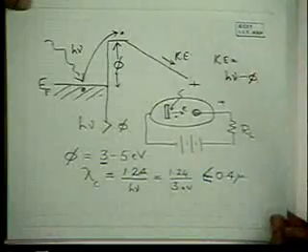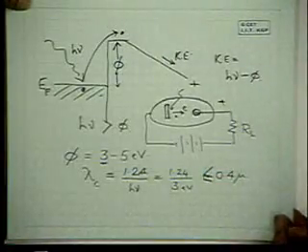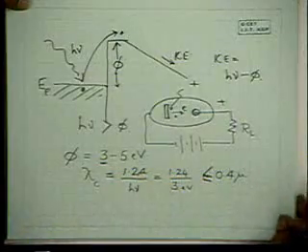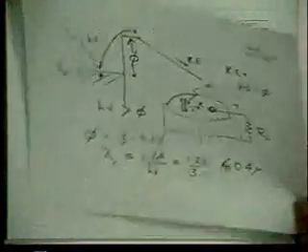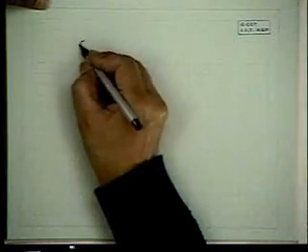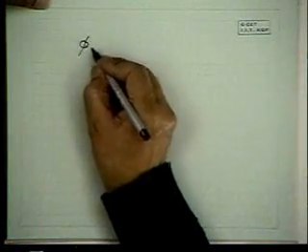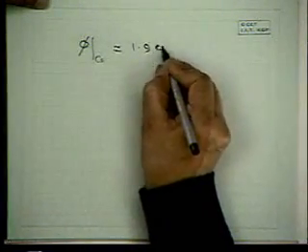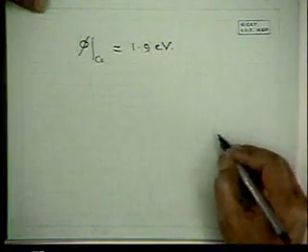So from the material point of view, if you want operation in the blue or in the visible range, obviously you have to lower the work function, and it was found that a material like cesium has a work function of only 1.9 electron volts. However, cesium is an alkali metal. It's not all that stable.